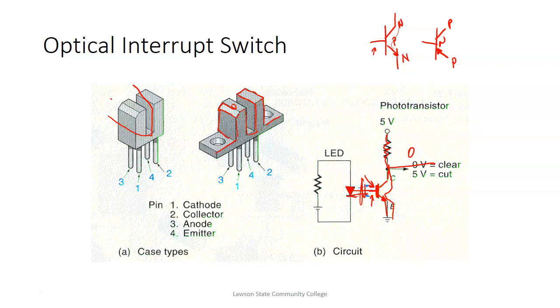They're nothing but through-the-beam, but the transmitter and receiver are in one unit. And we'll show you all these on the Amatrol line. So we have a gantry crane that sorts the valves, and the position that lines up with the magazines is going to be set by these optical interrupters. So we'll show those. I don't think we have any on the Festo line. I'd have to think about it.